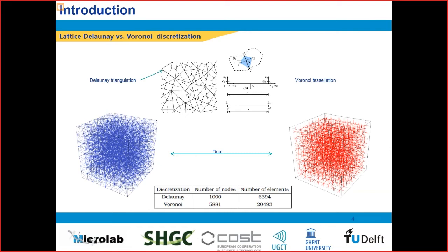Now, in the case of mass transport, Branko has already mentioned how the same network of beams from the Delaunay triangulation can be used to simulate mass transport, as if it were a system of pipes that are connected through the nodes, in which the degrees of freedom can be either the concentration of a specific species whose transport we are simulating, such as chlorides, as Branko mentioned already, or the moisture content, or, as you will see later, the pressure of a non-wetting fluid, such as CO2.